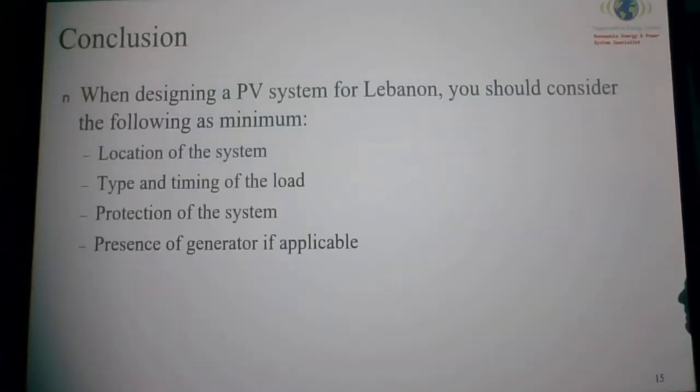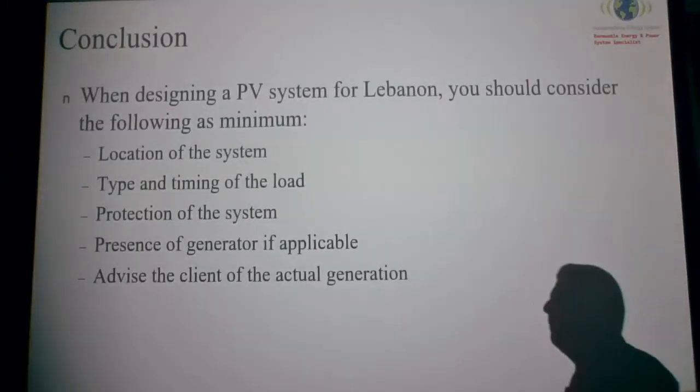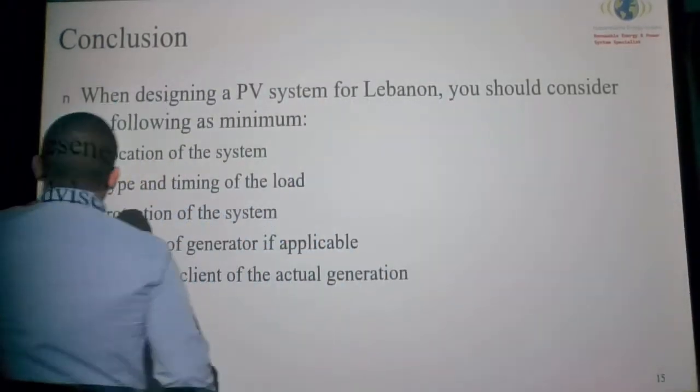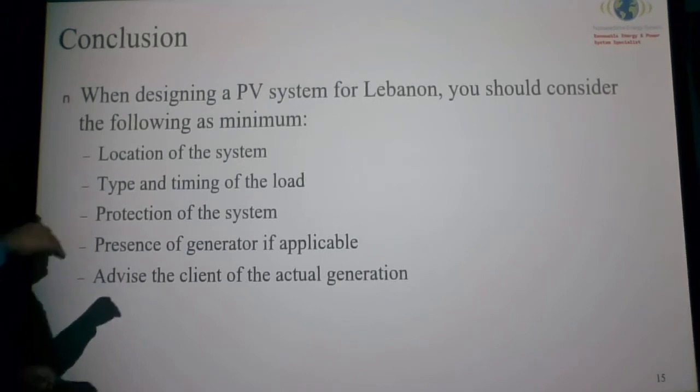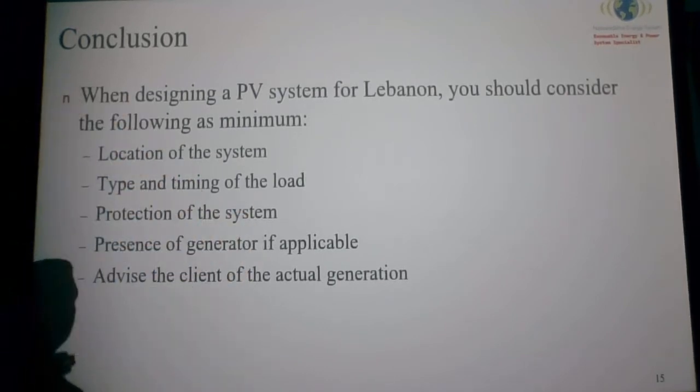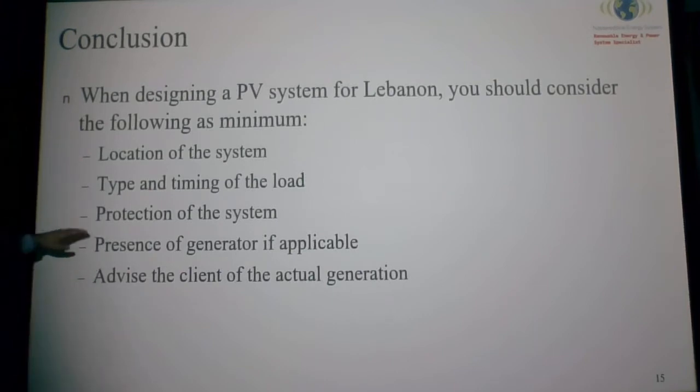Now, these are, guys, the conclusions. You need to focus on the location of the system. Is it on the coast or up the mountain, especially in Lebanon, or in the Bekaa Valley? Type and timing of the load: do you want AM, PM load? Do you want midday load? Protection of the system is very critical. If you have the presence of a generator, you have to follow strict regulations.